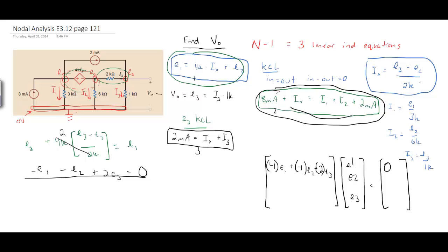But we have all substitutions for those currents to get into terms of E1, E2, E3, so that's not going to be a problem. And that ends up being, I'm going to skip it just because of time. You guys are free to either ask me or work it out and see if you get the same solution. Give you a little bit of practice. We have 1 over 3 E1 plus 1 over 6 plus 1 over 2 E2 plus a minus 1/2 E3, and that is equal to, I get 6.